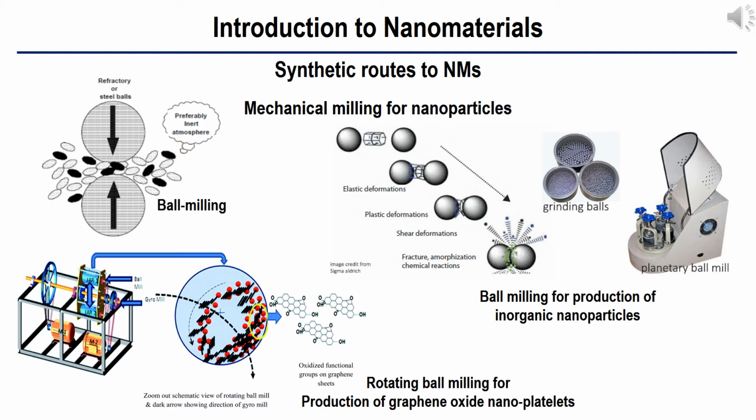This method of synthesis is suitable for producing amorphous or nanocrystalline alloy particles, and elemental or compound powders. If the mechanical milling imparts sufficient energy to the constituent powders, a homogeneous alloy can be formed. Based on the energy of the milling process and thermodynamic properties of the constituents, the alloy can be rendered amorphous by this processing.